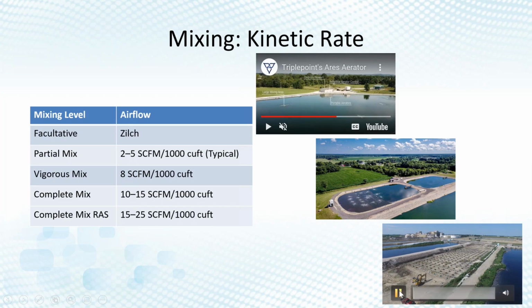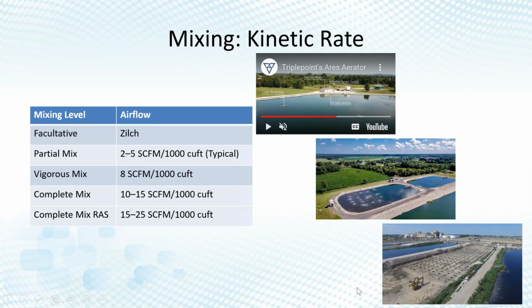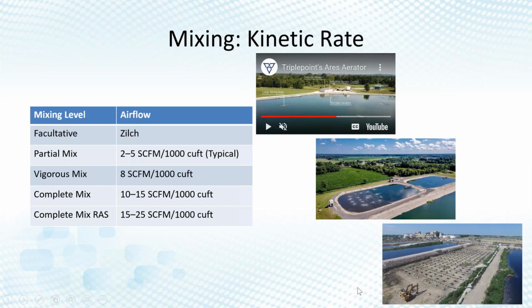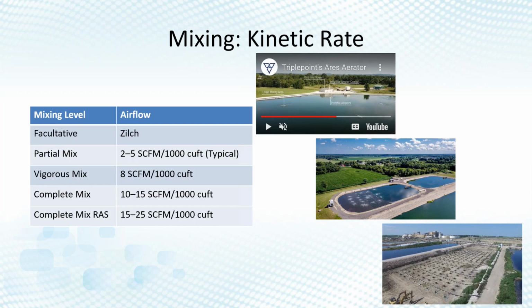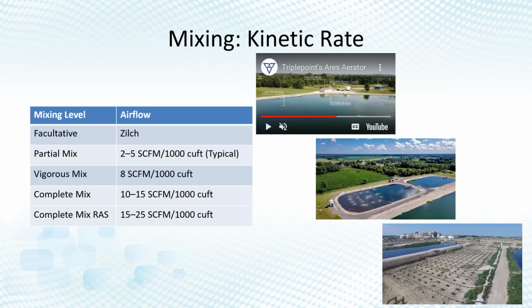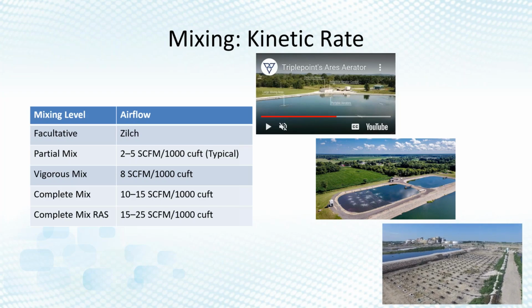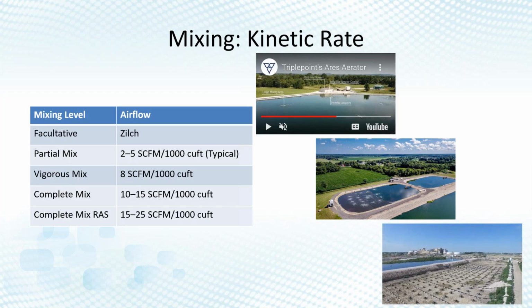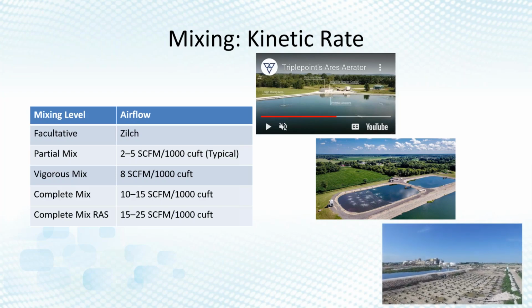And lastly, you have complete mix, and this is what complete mix might look like if the water's drained. We tend to do this mostly industrially when we need that level of air, but as you can see, the aerators are really close. We got a ton of them out there, and there's no dead space whatsoever because we want every solid that comes out here to be kept in suspension for rapid treatment.